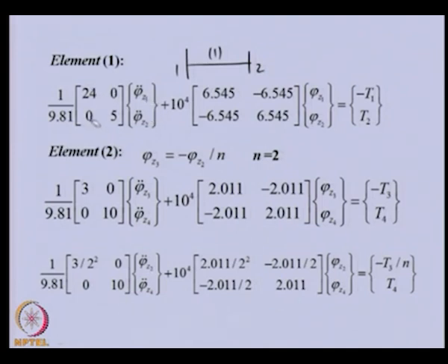Here we are not considering the shaft inertia property, only the polar moment of inertia of the flywheel and the gear. So, in this particular case we have not considered the shaft inertia, only the lumped masses at the ends have been considered.